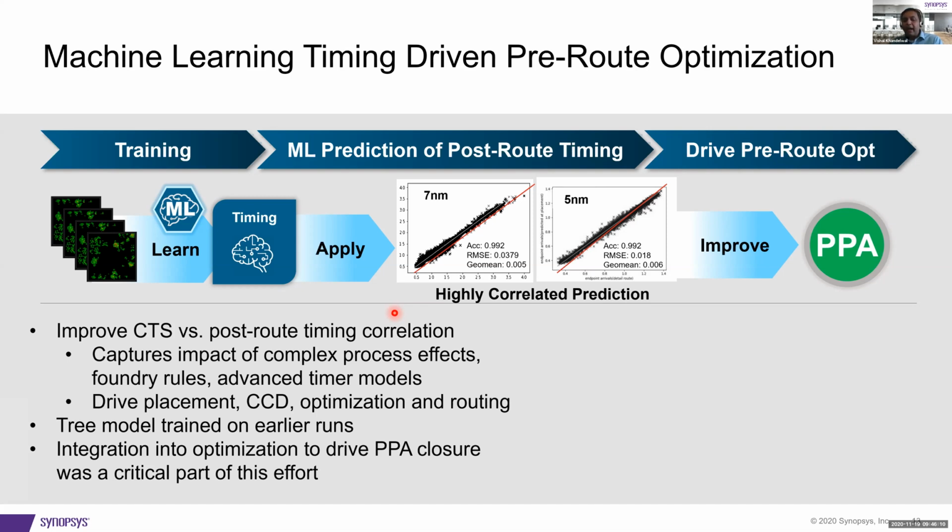And why does it matter, right? When you have engines like global placement or global skewing, these engines are really feeding off global timing. If you don't have a good sense for your global timing, the trade-offs you're making here could be hurting you or leaving quality on the table, right? Both happen. And it's very late in post-route to really fix many of these issues. So the sooner you can align your timing or improve your timing correlation, the better your convergence and PPA is. So we've done some interesting work here.